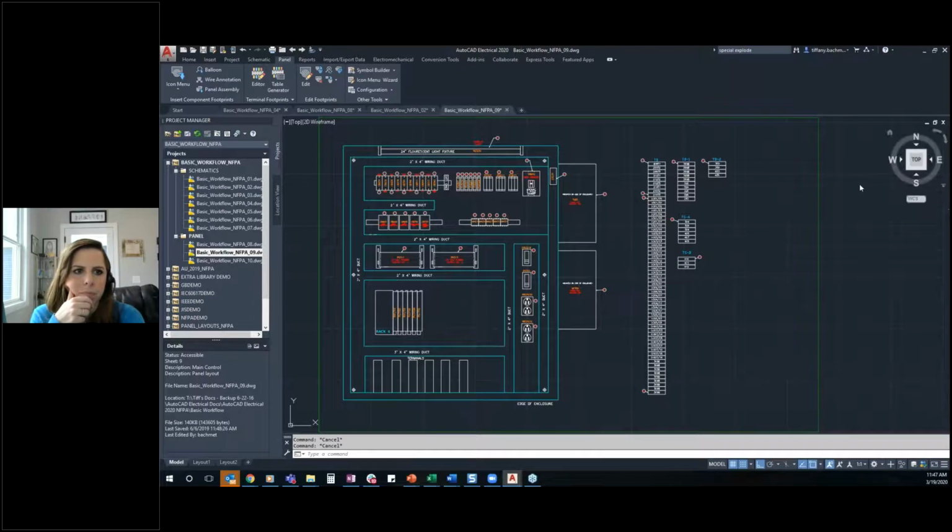Yeah. But the follow-up is that if we could add in the command, so when you copy in, say you're adding another input card to a blank slot on a control objects rack. I'm taking an input card and using the copy drawing. And if that drawing already exists in the project, it doesn't invoke the prompt, hey, I found duplicate terminal identification numbers. Do you want to make these unique? It basically just copies it and overrides it.